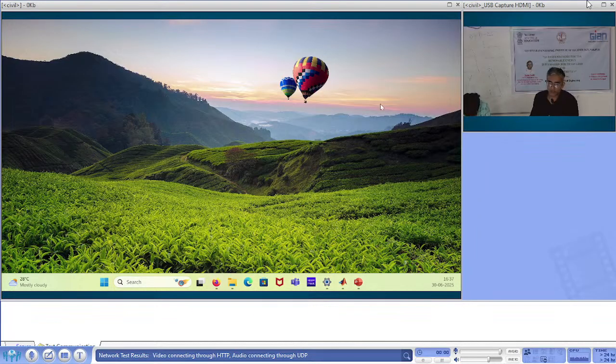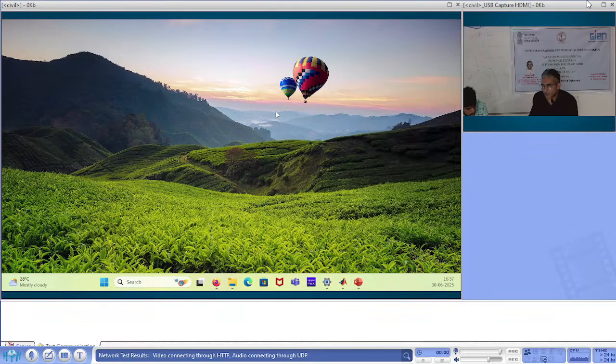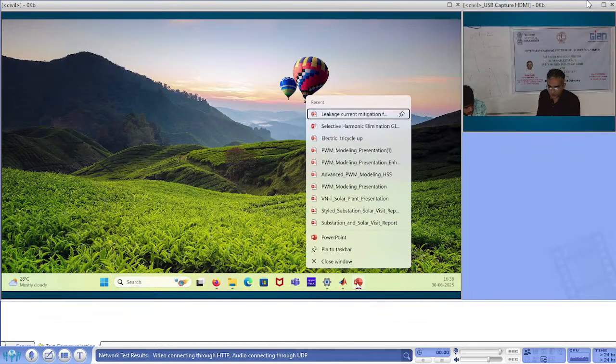So what is the advantage of this? Most of the ripple is absorbed by the inductance, and then you have a reduced value of capacitance. So the life of a current source inverter is higher than the voltage source inverter for the PV system. Because you are reducing the electrolytic capacitor value, as most of the stress or ripple in the system is taken care of by the inductance.